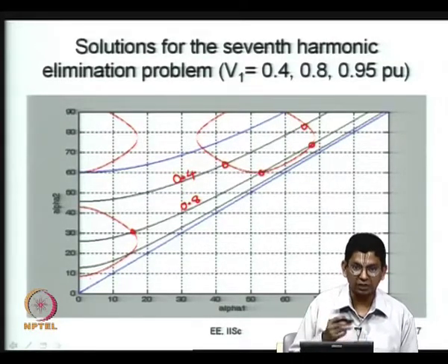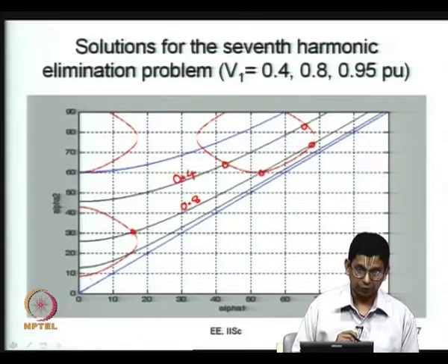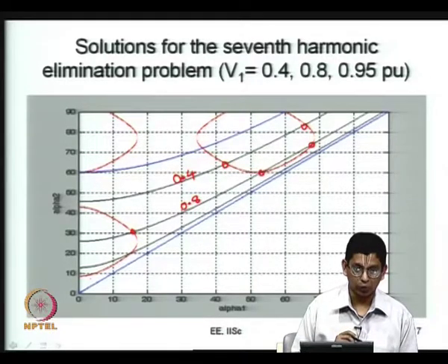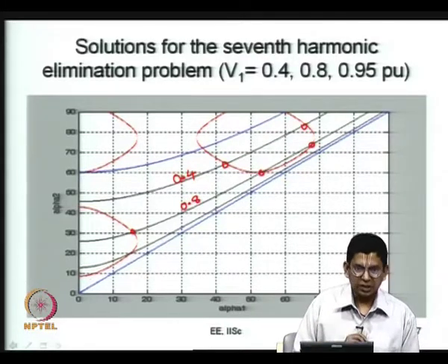Firstly, we should be aware that options are available, and then evaluate the options. For evaluating the options, we should know what criteria we would like to pose. So, one of them could be V phi being 0, one of them could be the weighted THD of voltage being low, another could be the pulsating torque, let us say the 6th harmonic torque being low, etc. So, now these 3 points are there in this range.